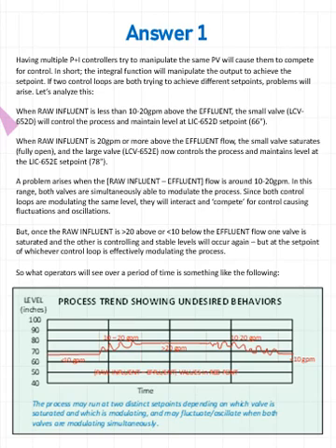Especially the large valve. As the large valve barely starts to crack open, it's going to cause major fluctuations on the small valve, and of course the small valve is going to react and so forth. You're going to end up getting some fluctuations and even oscillations. In the real world situation on this, they're pretty notable oscillations.